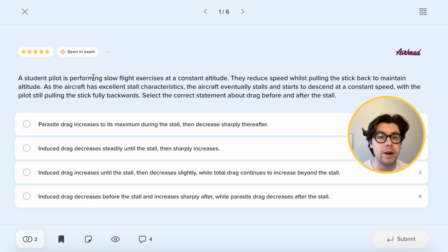For the exams, remember that the critical and stalling angle of attack is still not stalled. The meaning at alpha crit, we will have the highest possible alpha. Anything afterwards, the aircraft will stall. Then also remember, especially for the exams, that a spin is also a stall. If we are going downwards in a spiraling motion, this will be a spiraling dive. And this will be everything for just a brief introduction, and I'll try to give you more tips and details as we go through the questions right here.